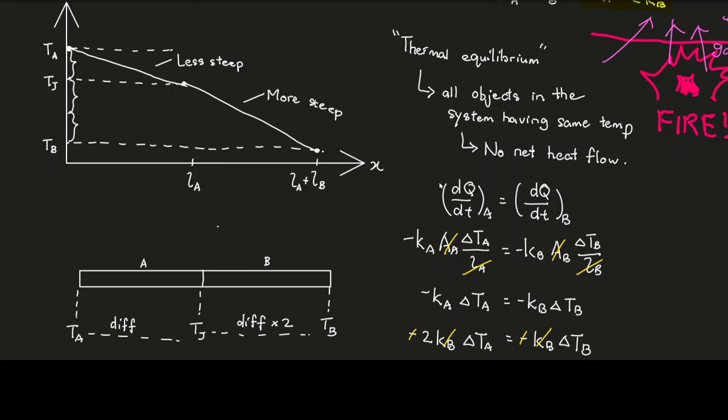So if there's heat loss, then the graph should probably look something like this, because this difference in temperature that you see here is due to heat loss. Loss of heat, and therefore temperature will get smaller. So that's the idea if something is having non-insulated rod.